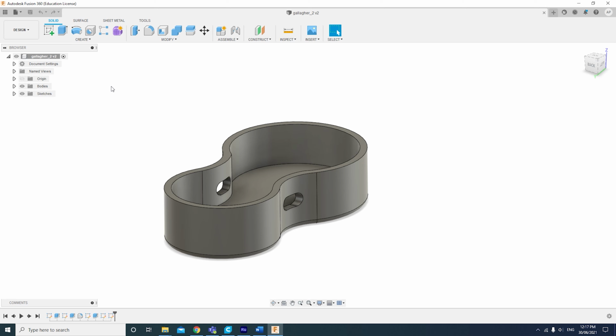So it's not proprietary. However, once you save it as a mesh file like an STL, you do lose a lot of the geometry and features. So it's important that you also have a version of your solid model still saved. Otherwise, it can be quite difficult to come back from. Essentially, this surface here would become a load of triangles. You wouldn't be able to create a sketch on the plane and edit it as easily as you can with a step or a Fusion 360 native file format.